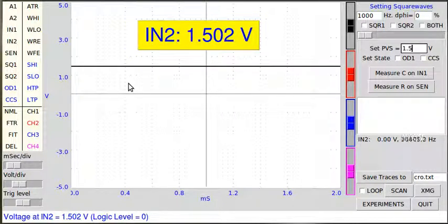Here you can see that the measurement accuracy of in1 and in2 are better than A1 and A2. So if your voltage to be measured is positive and from 0 to 5 volt range, use in1 or in2.